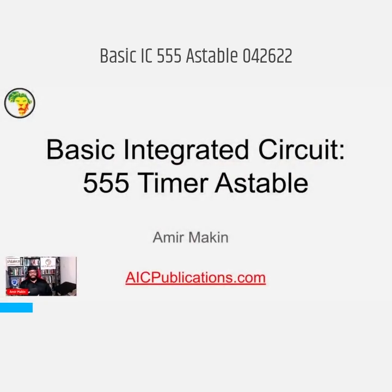Today's tutorial is going to take you over the basic integrated circuit. We're going to be using one of the most widely used integrated circuits. It's called the 555 timer chip, and we're going to be using it in an astable mode. That is a fancy term meaning we're just going to output one pulse at a time. The pulse is going to be indicated by a light emitting diode, and that's how we'll see the pulse. And we'll have a timer hooked up to the circuit so that we can verify that what we've done is correct.